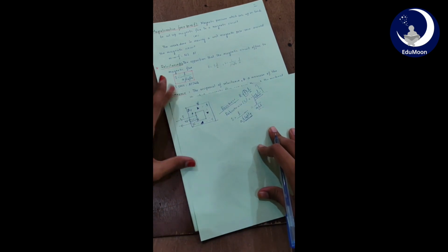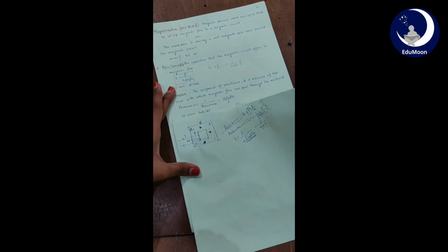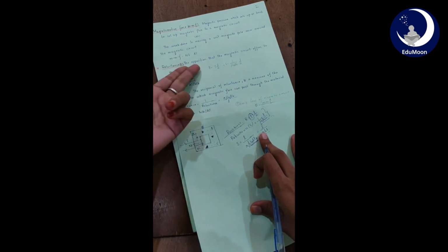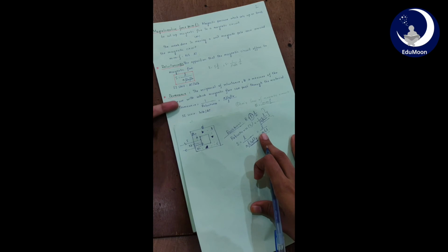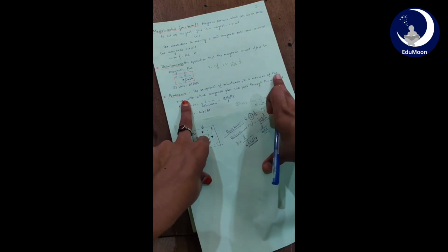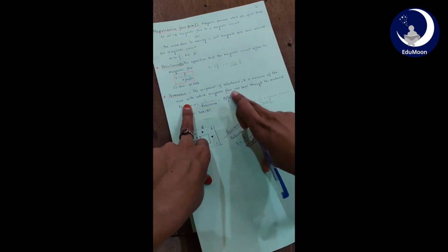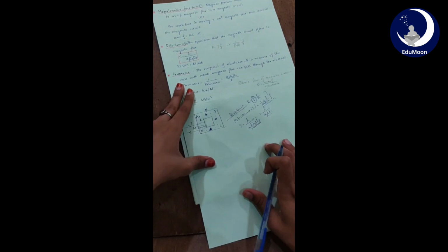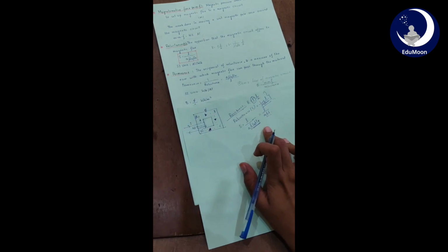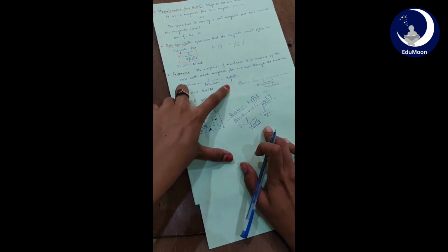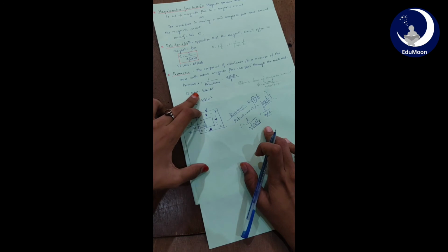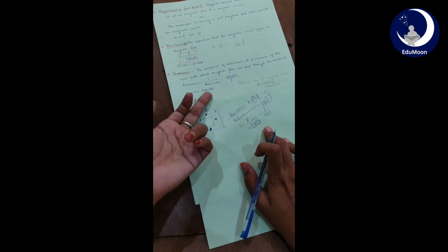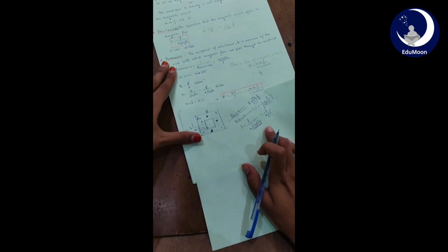So this is reluctance. Now we will see what permeance is. Permeance is easy. It is the reciprocal of reluctance. Reluctance is opposition; here it is ease. Permeance is the measure of the ease with which magnetic flux can pass through the material. So permeance equals 1 by reluctance, that is A mu naught mu R by L. Obviously, its SI unit will be the reverse of reluctance: Weber per ampere turn.